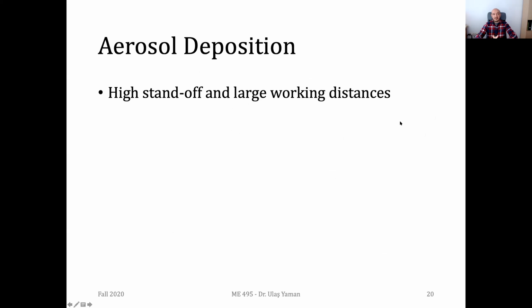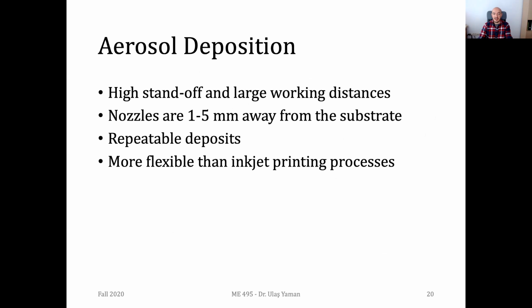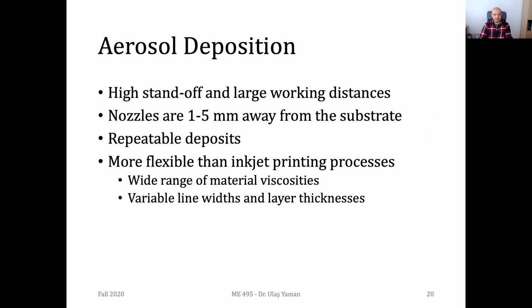In aerosol deposition, you may have high standoff and large working distances, so you don't need to be closer to the surface. There might be a gap between your surface and the nozzle. As you see, they might be even 5 millimeters away from the substrate. You can have high repeatability, and it's quite flexible compared to the other inkjet printing processes.